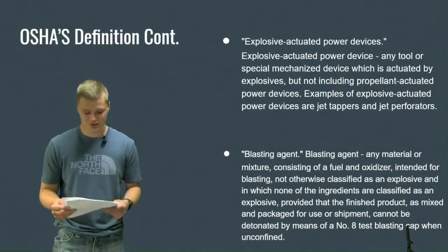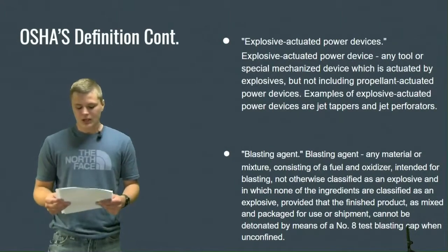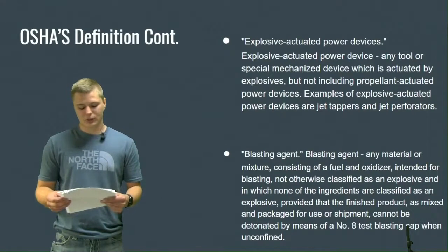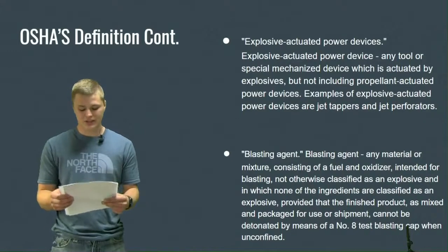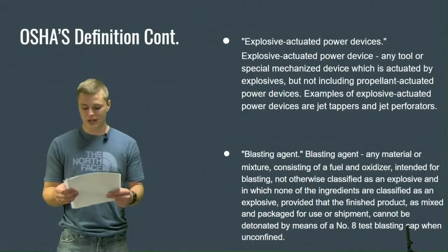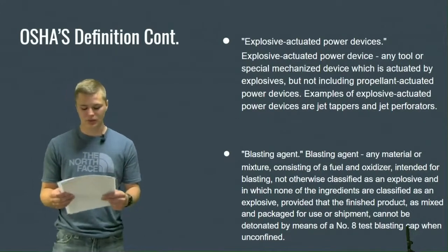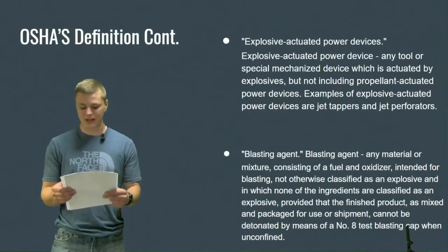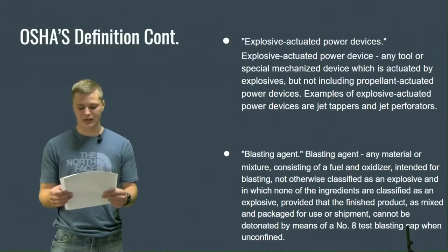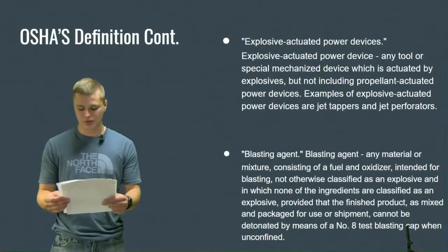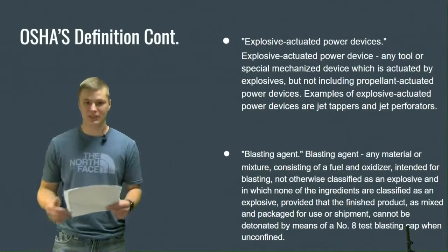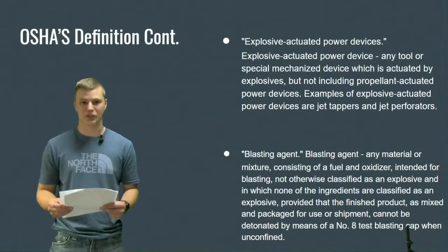Next are blasting agents. A blasting agent is any chemical, material, or mixture consisting of a fuel and oxidizer intended for blasting, not otherwise classified as an explosive, and in which none of the ingredients are classified as an explosive, provided that the finished product, as mixed and packaged for use or shipment, cannot be detonated by means of a number 8 blasting cap when unconfined.